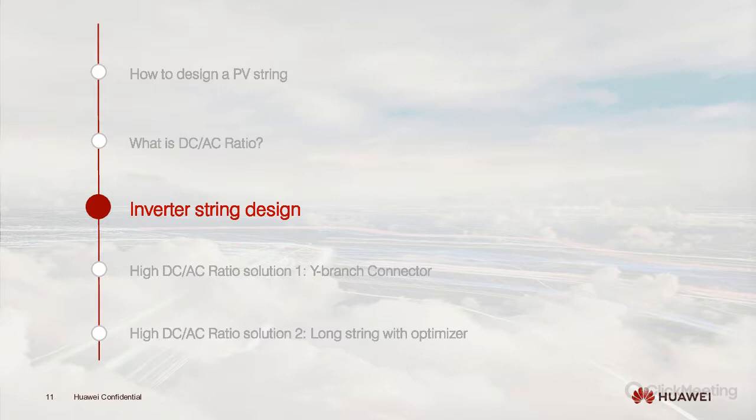So the next factor we will be looking into in a bit more detail is the inverter string design. When we look at inverter string design itself, we need to be looking at what is the most suitable type of string and the oversizing that can be comfortably achieved correctly for the inverter to perform at its maximum power.